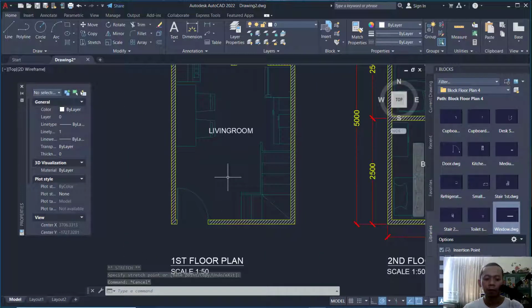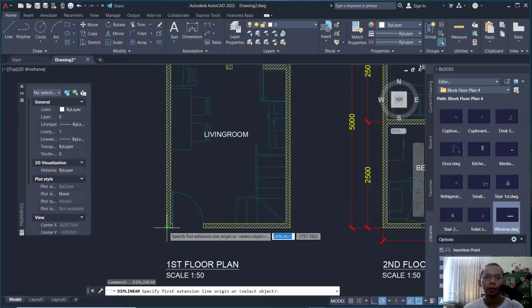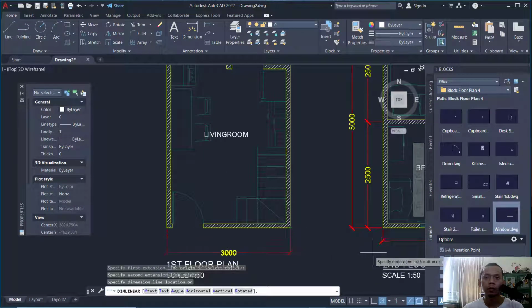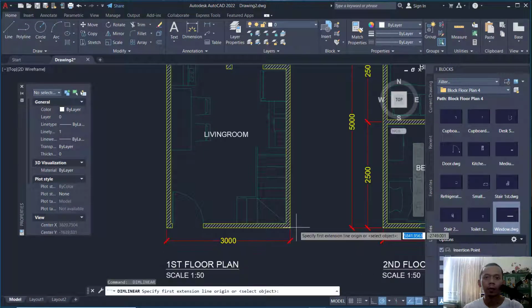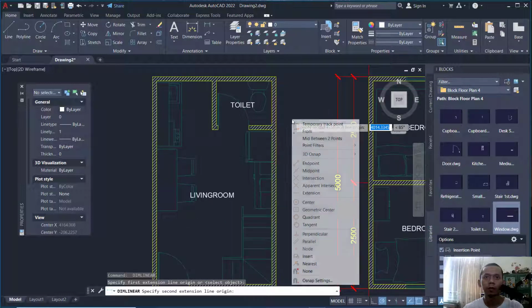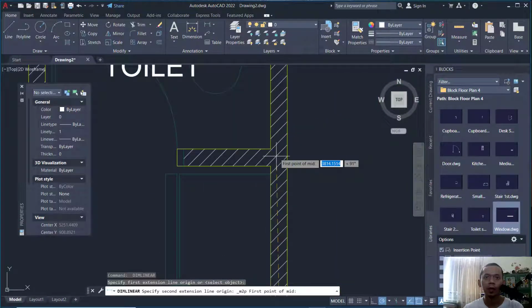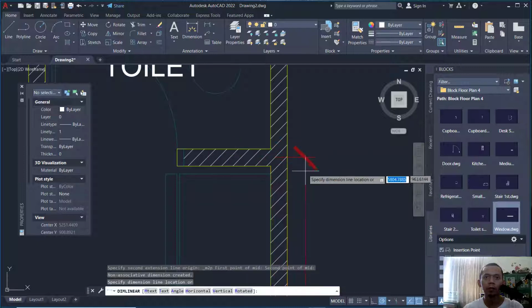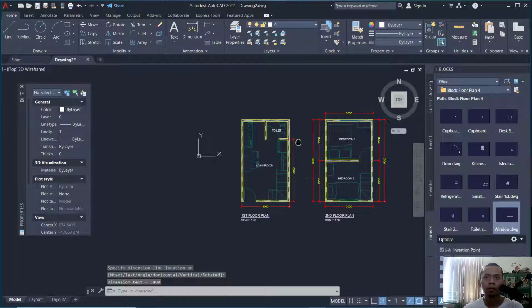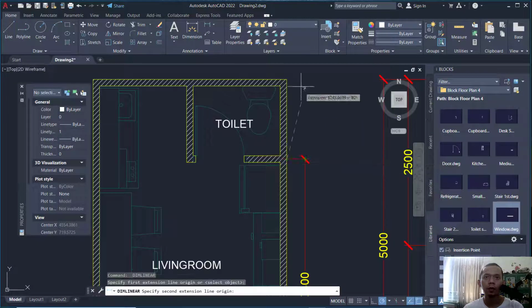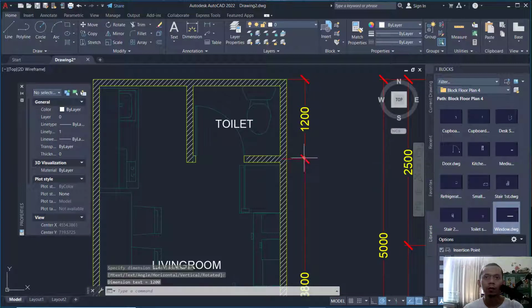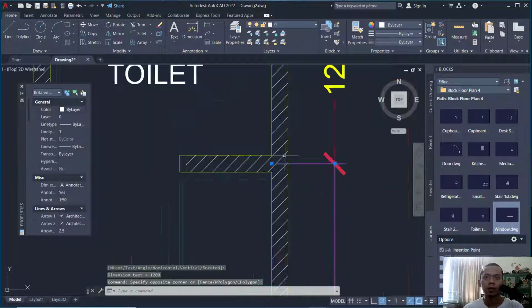And for the first floor, use a dim line in here. Okay, in the right here, use mid between 2 points. We select from these 2 points. Okay, to this point. Select this dimension. We can move into here.